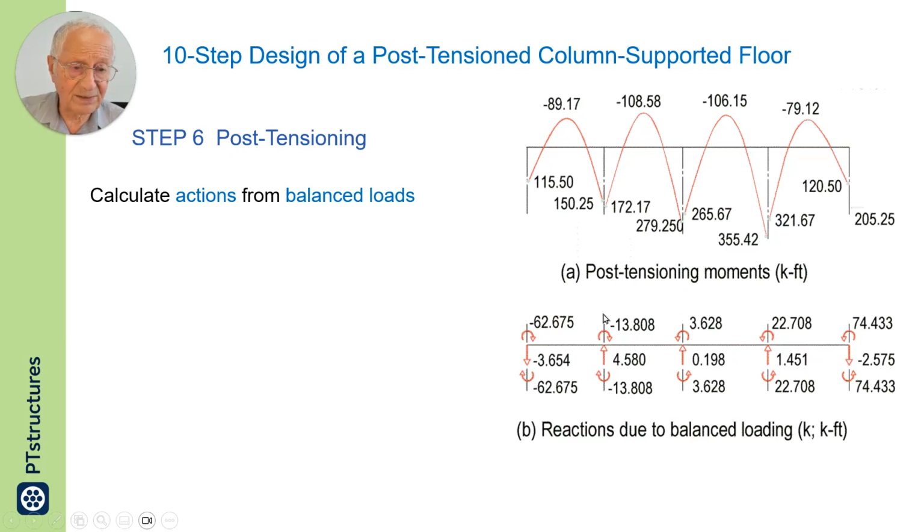created by the reactions. I use the moments at the top to do stress check, to do deflection check, but I use the bending moments at the bottom for safety check. The one at the top for service condition, the one at the bottom is for safety condition. So we calculate the actions from balance load, and these are the actions.